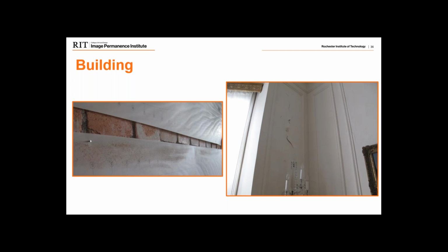You can also see, if you look closely, that there's some brick dust that has accumulated, and so you can see how the brick is starting to deteriorate as that moisture is moving from one source of moisture to a source of lower moisture. And then in the image on the right, again, there was a different level of humidity in the structure next to this one, and so we start to see this peeling paint.